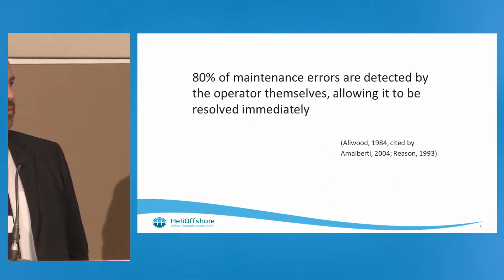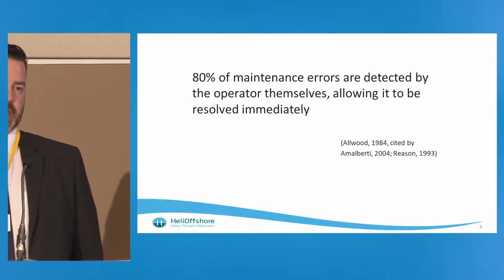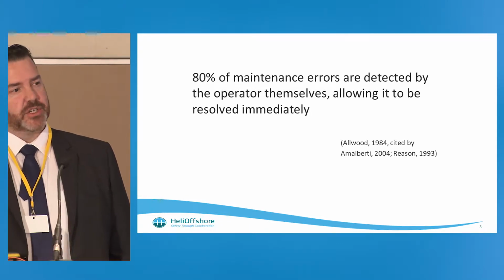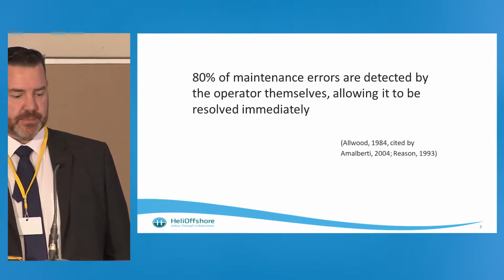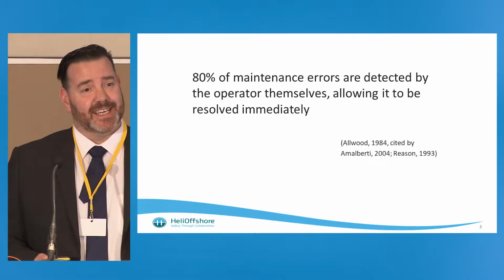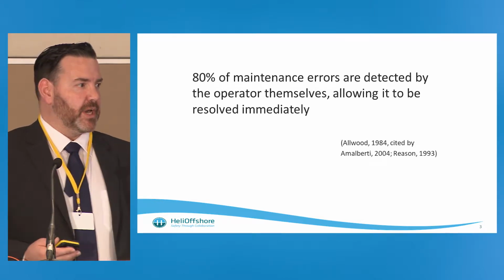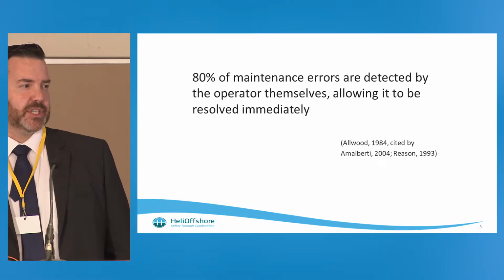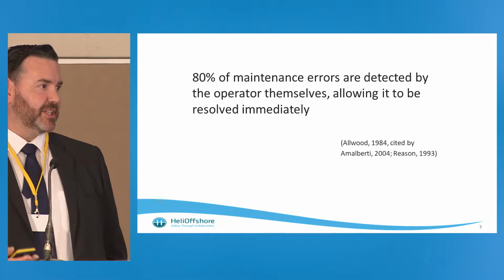errors do occur within maintenance during the practice of maintenance, so during the evening's line check, during the base check. There's many errors that do occur on a natural flow through the process. However, the system itself, the Part 145 system itself, is designed to capture errors as they occur. That's why we have functional checks, why we have duplicate inspections, why we have operational checks that follow the maintenance task of replacement, installation, or servicing.